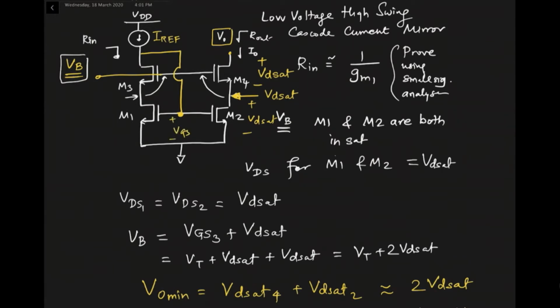Okay, VGS. Now, the value of the VGS, if everything is designed correctly, is based on VDSAT. If you look at transistors M1 and M2, they have exactly the same VGS and also exactly the same VDS. Just because of that effect, you're taking care of the lambda effect, or the channel length modulation effect. In the previous one, you could end up in a situation where in a simple current mirror, the VDS could be different, and as a result the lambda effect comes in.